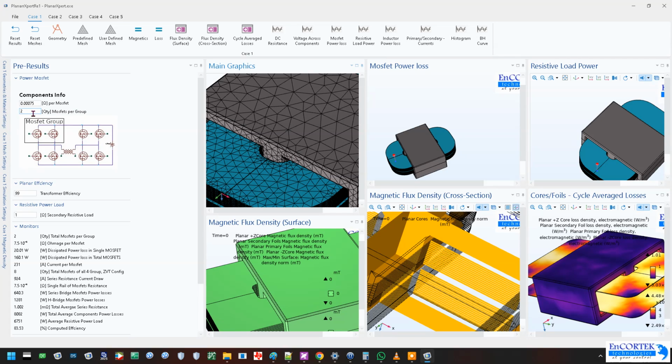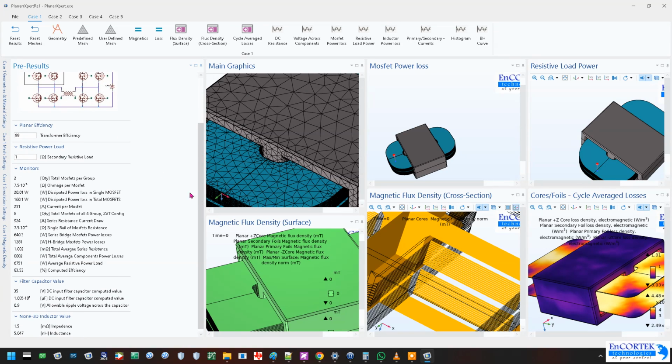So when we increase the MOSFETs, we increase costs, but we decrease the ohmage and losses, right? But the thing about it is that we increase capacitance to the gate. So we have to take into account all these different areas. We just lose energy in the drain to source capacitance and the diode region itself. So it's important. We have to look at every loss. Like faster switching means more losses, depending on the components that we're using for switching.